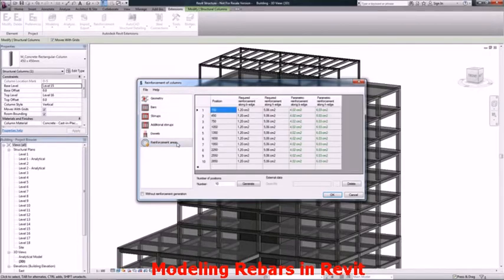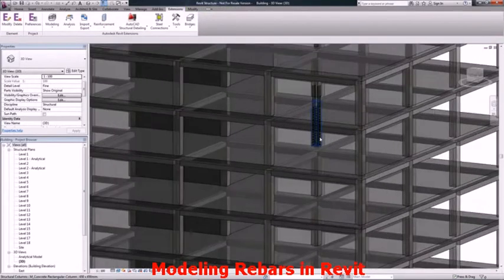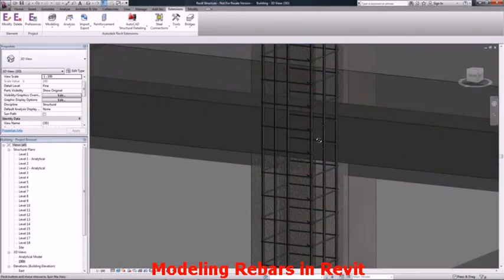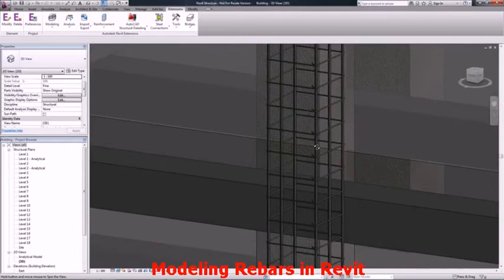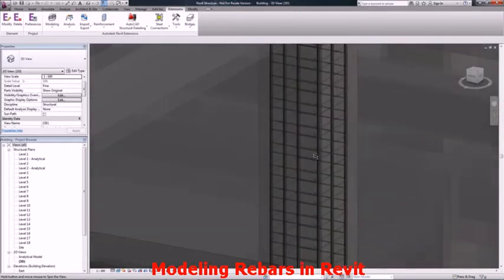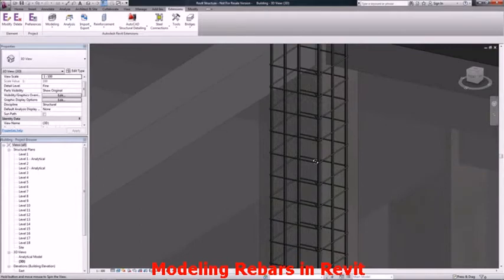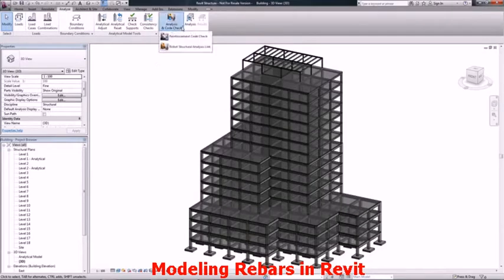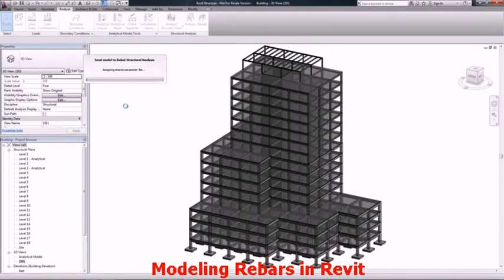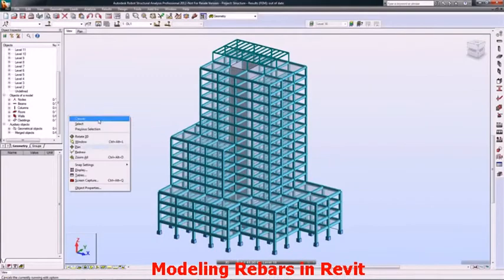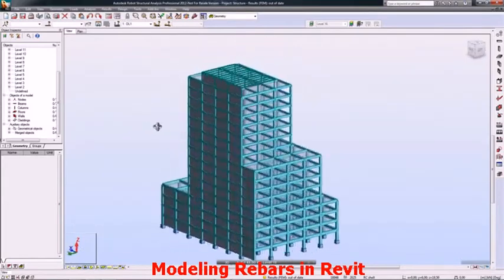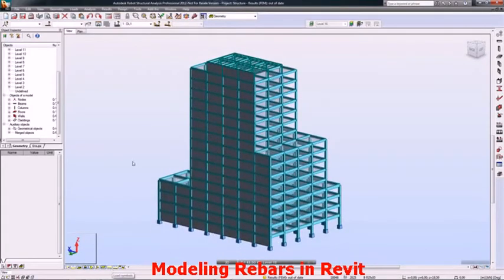Another benefit of the bidirectional link between Revit Structure and Robot Structural Analysis Professional is that after the designer transfers the model again to Robot Structural Analysis, all changes are maintained. As you can see, information such as meshing parameters and additional loads is preserved during this iterative process. This is an important aspect because the link mechanism preserves this analysis-centric data and ensures complete integration and preservation of data across multiple links of Revit and Robot. And now an engineer can perform analysis and design once again.